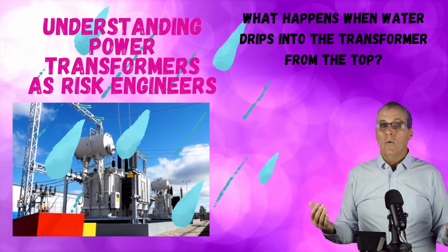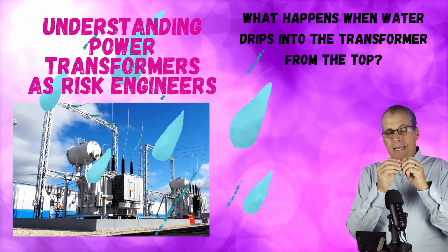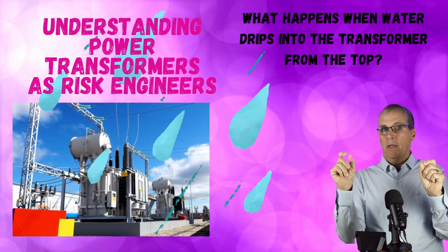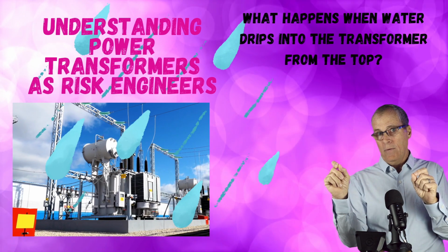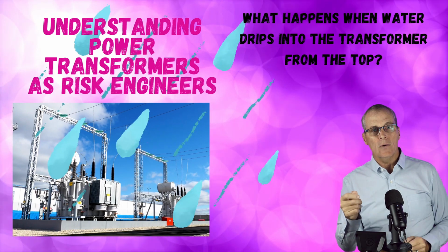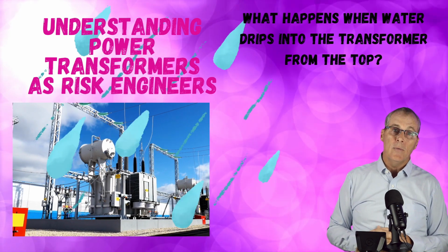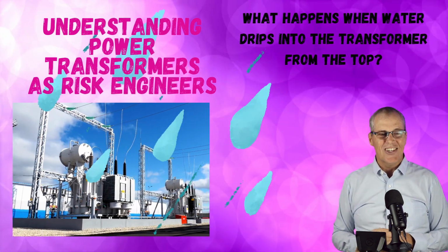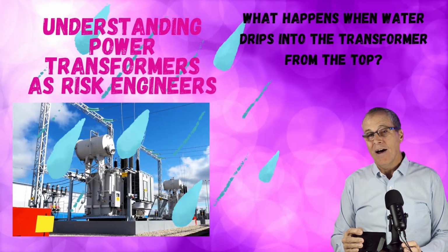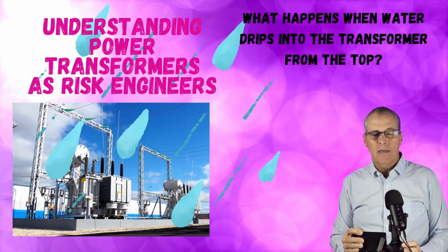And what is going on? Well, as the water replaces the oil in the paper, the insulating ability of oil and paper is much better than the insulating ability of water and paper, right? So as we become more like water, eventually we have no insulating ability and we get a fault. Fortunately for the site that we had down there, we didn't have an explosion or a fire, but we did have a fault. It was a challenging insurance claim, one that started off a little shaky because it had to do with overtime and corrosion and all that, but it ended up getting paid.